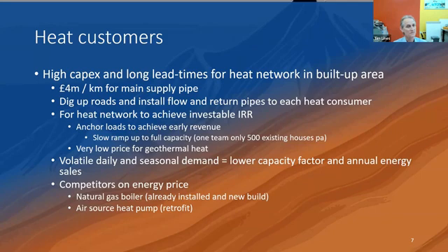Heat customers: I know you're not looking to sell heat, although I might ask you to pause when you put in your field development plans about just how much heat you are not using. So if you've got a typical organic Rankine cycle or steam turbine cycle, using a binary cycle with heat from the reservoir, and you generate your 50 megawatts of electric from that, there's probably going to be roughly 15, or maybe if you're lucky 20%, of the thermal heat that you've extracted in your heat exchangers.